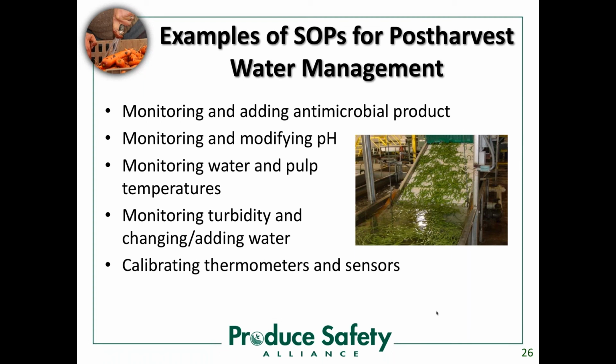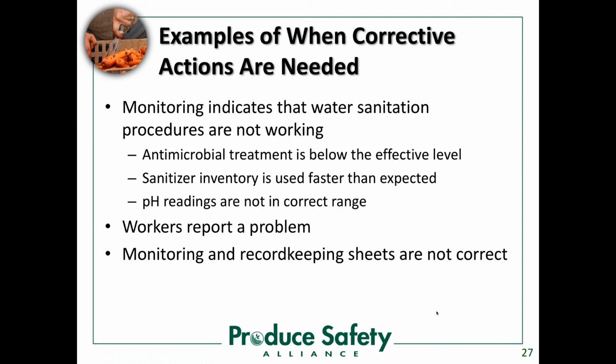So that's something that was really driven home to me when I went through this course initially, is to learn about this infiltration issue. We've talked about the turbidity question, and also something there, calibrating thermometers and sensors. We can't just get equipment and not calibrate it. If it's intended for measurement and monitoring, we need to calibrate it periodically so that we know that it's still working as it was designed and giving us good information. Otherwise, we might not like the result.